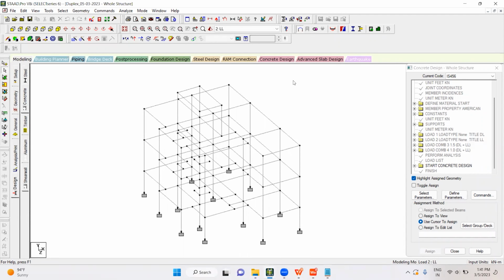That would be all right to use and check. So there are some guidelines, or key factors. Even for beams, for plinth beams, use 230 by 375 up to a certain span, and for floor beams, use the beam size given for the span. Since all of them are already given here, we use those guidelines, assign this structure, run this analysis and design it. So it is done.